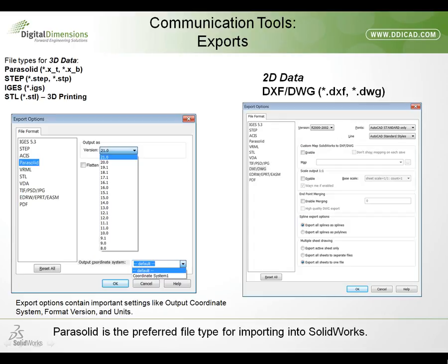One of the advantages of using a different coordinate system is if you import a file from another CAD system and the origin is nowhere near where you need it. After all, we need to remember that the origin is the intersection of the standard three planes, and perhaps moving the origin closer to the part so it's usable. For example, in an assembly we can use planes for mating. If the origin was placed in the middle of your part, you could then center that part in your assembly,